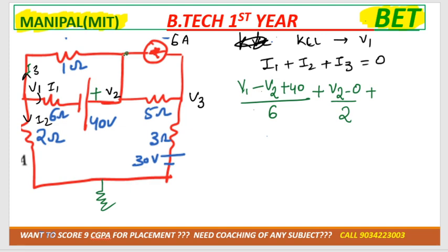V1 to... we can convert this current source in parallel, right? We can convert this current source into the voltage source also. That will be easier for you. Otherwise you have to take another node. Okay? So converting would be easy, because after converting it would be reduced to a single mesh. So see how the diagram looks.